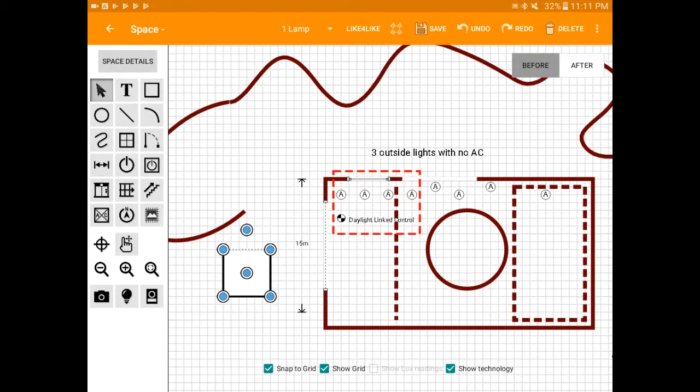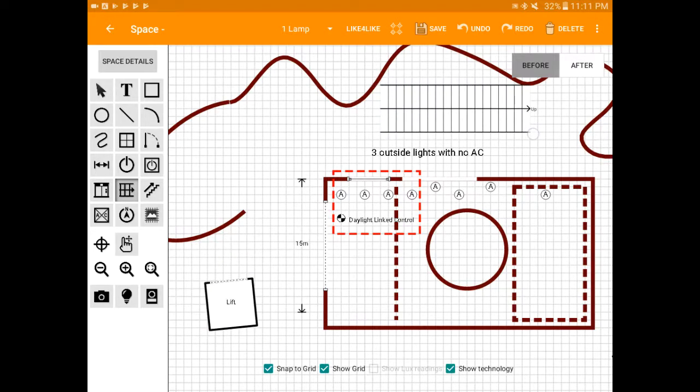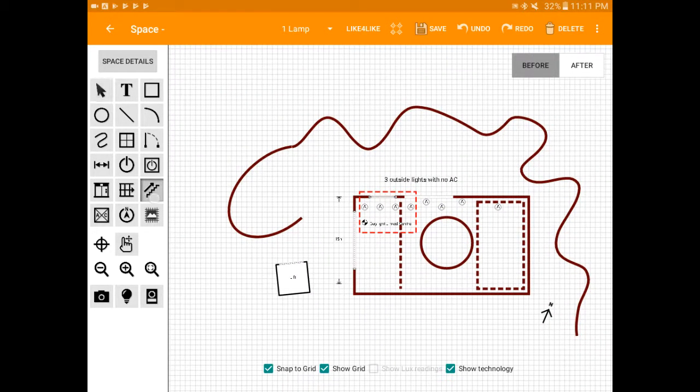We also have a lift, elevator, so you can show on the floor plan where the lifts are. It's just for orientation really. Also got a few different types of stairs. They can be rotated, made wider or shorter, whatever you want. Just delete that one. And then you've also got these stairs, but you have to think of this staircase as looking at a fire stair from side on, because the rest of this view is always bird's eye view, looking top down. But imagine you're looking side on for this stair, and you can just add more levels as you go.